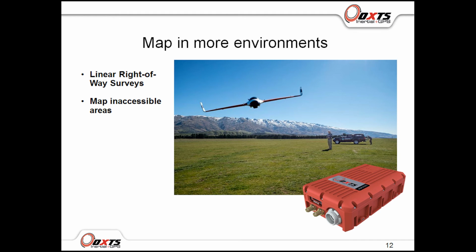A direct georeferencing workflow can lead to reduced fieldwork time and the ability to map ever larger areas. Due to the overlap requirements of aerial photography when mapping linear features, such as transport networks and right-of-ways, direct georeferencing can enable mapping operations to be potentially carried out using fewer flight lines and fewer ground control points.